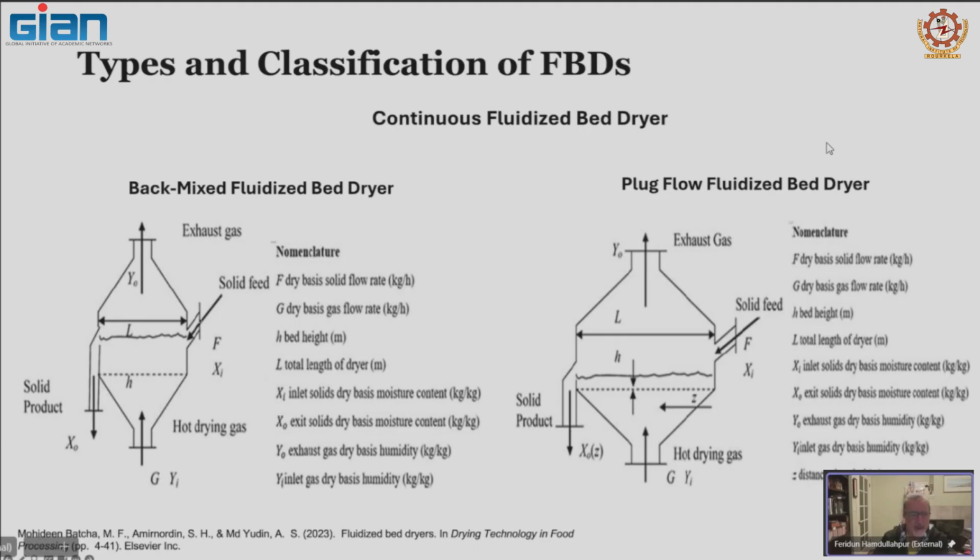If you start with smaller surface moisture, you need your dryer mostly to remove the moisture that's trapped inside the particle. Then you want it to spend more time within the dense bed, to benefit from all the agitation and mixing inside the bed.